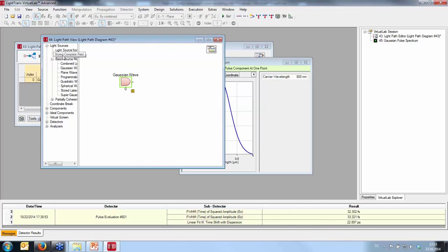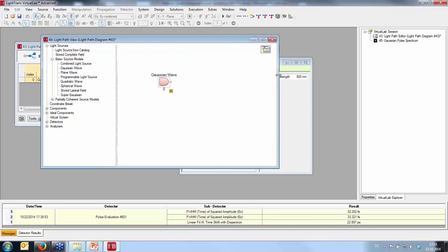And now I will place a sinusoidal grating in our optical setup. Here we have different opportunities, so we can simulate real gratings and idealized gratings. The difference is that in an idealized grating, I do not have to know the exact structure completely. I can just assume, for example, a certain period, and I use some approximations to solve the problem of the light propagation through this grating.